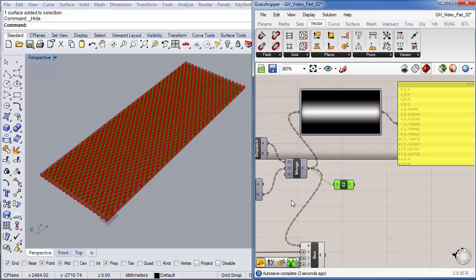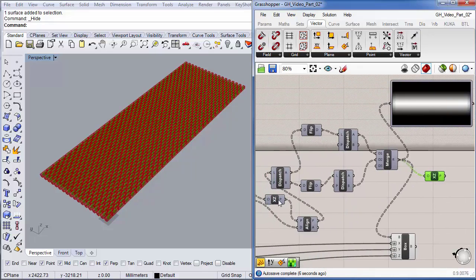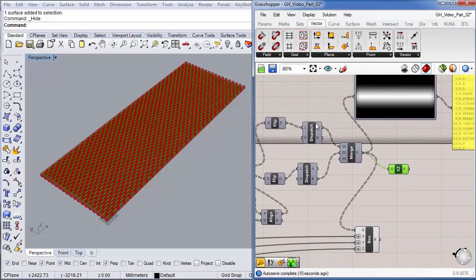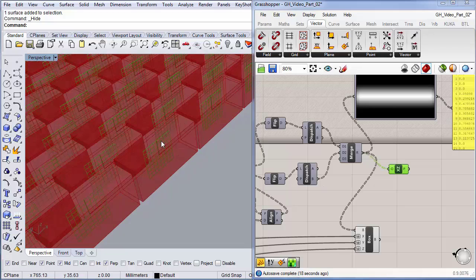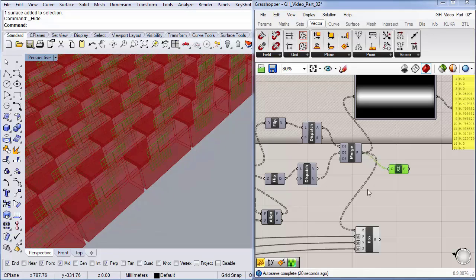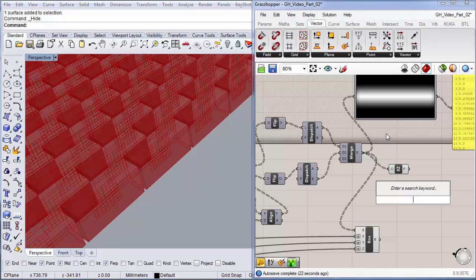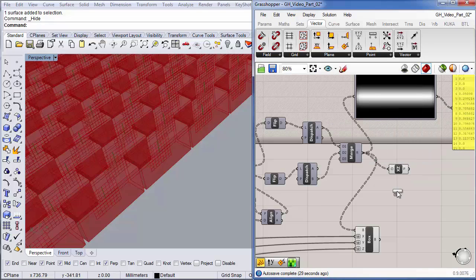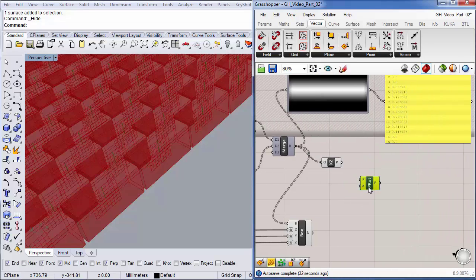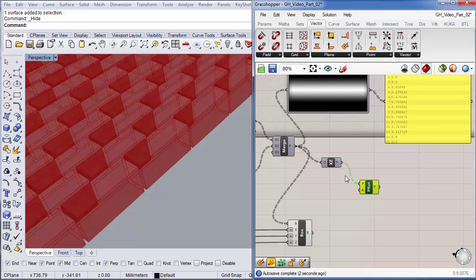All right, so it looks like it's repetitious of these planes, but it is a list of planes in a much different order, because we've gone through and played with the order here to get where we were going. If I look down, they're still similar planes, but now I'm going to use those planes and rotate them. So I'm going to come back to plane, go to somewhere here, Rotate Plane. This needs a value. It needs a plane to rotate, which we'll give it. I'm going to hide these as we're moving along.